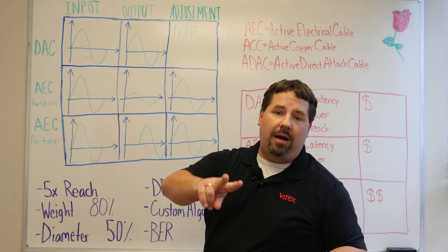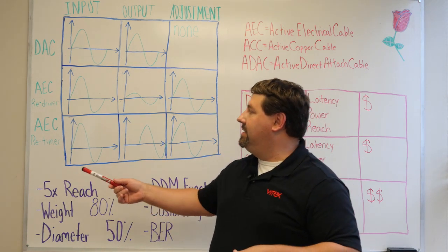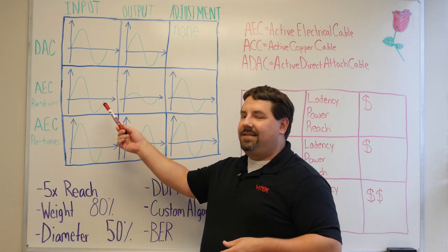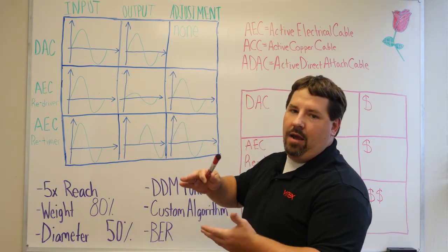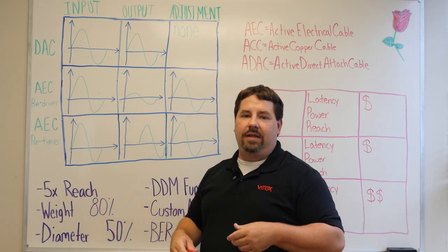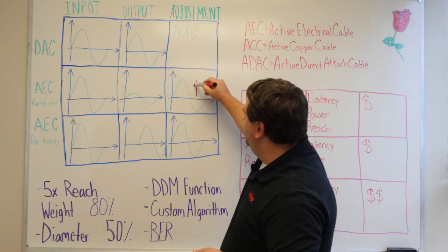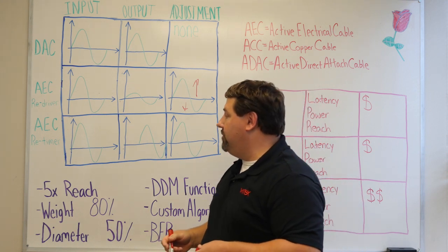You have two options that you're really going to look at from a technical standpoint. One is the redriver. This is important because as the signal goes farther and farther, you're going to lose amplitude. To get that back, we need to apply more gain to it. This is what the redriver does. It allows us to increase the gain on our signal and results in a longer reach.